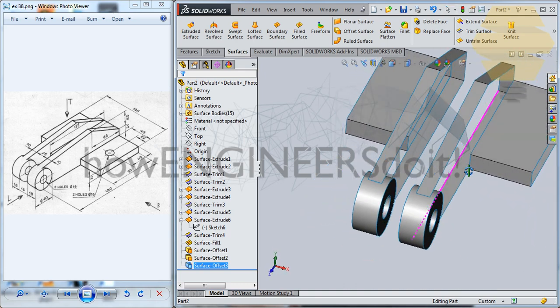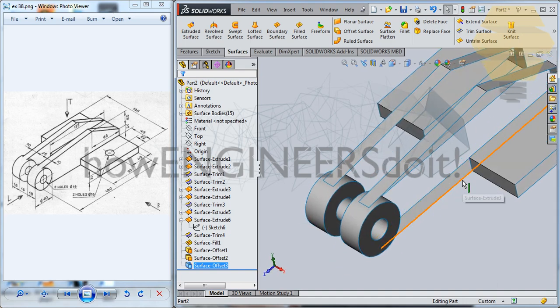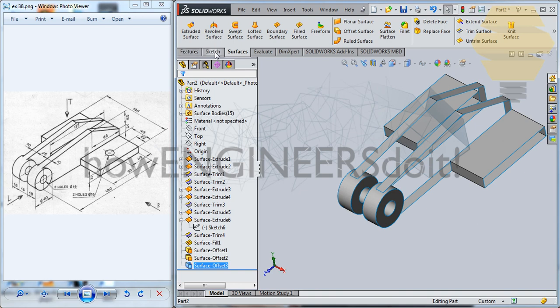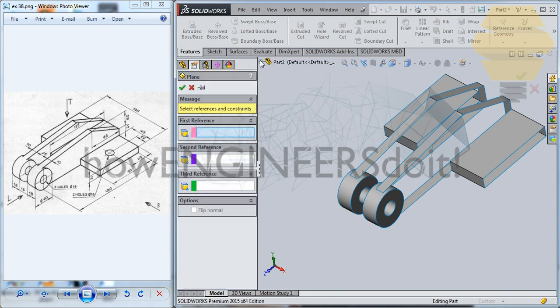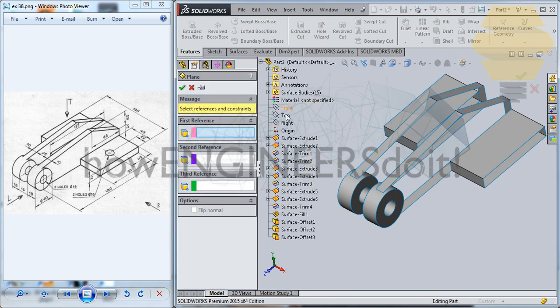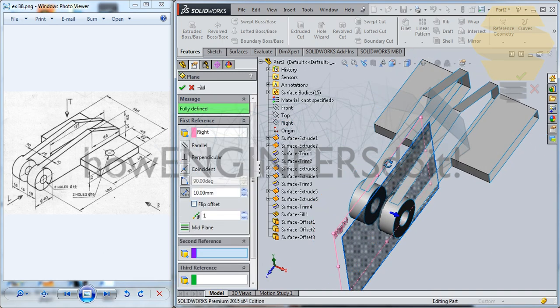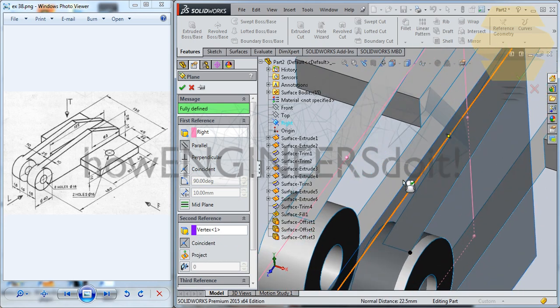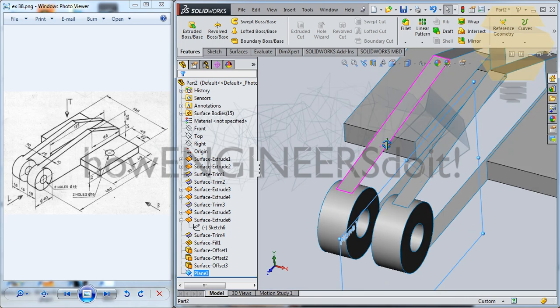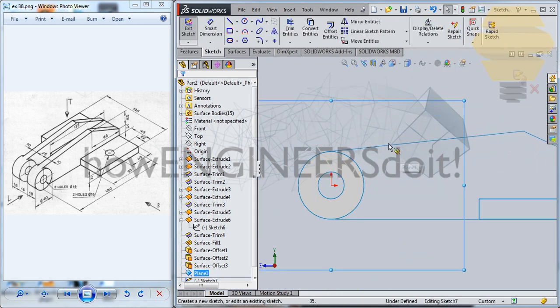Now what we can do is we'll just go for features, create plane, from the right plane, gotta create a plane. This point, tick mark. I'm gonna select that plane there and go for the sketch.